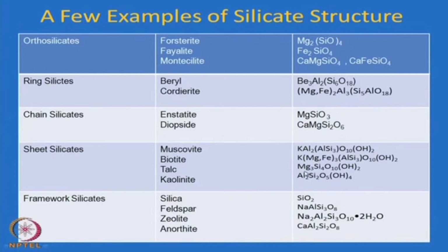So, talc is basically a naturally occurring mineral and is a silicate structure, and these silicates either have what we call a symmetric structure or an asymmetric structure. Like kaolinite, as I discussed, is an asymmetric structure, one layer of silica and one layer of aluminum hydroxide, whereas muscovite is basically a symmetric structure with two layers of silicon oxygen, and in between you have a layer of aluminum hydroxide.